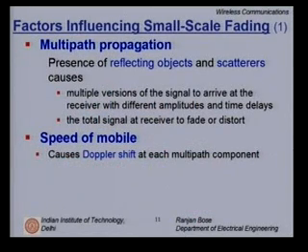So now you are vectorially adding up the copies of the signal which are delayed, changed in amplitude, changed in phase, and the frequency modulation has also taken place. Then you vectorially add up. So consequently, what you receive is very different from what you send, and we have to somehow overcome the effects of fading.